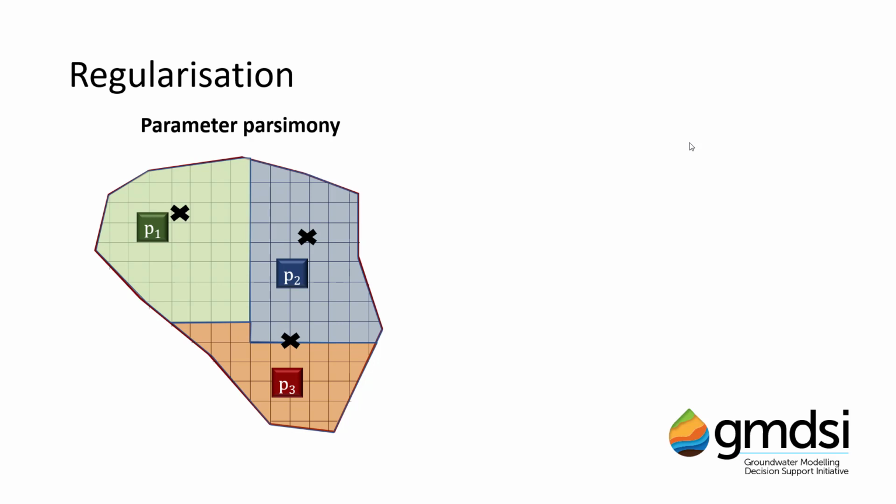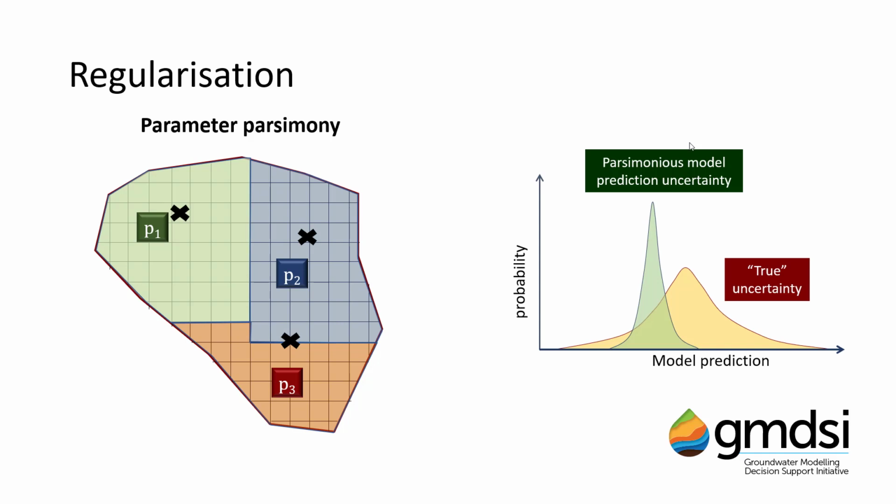These zones will have been delineated based on subjective choices by the modeler, and too few zones decrease the ability of observations to actually inform parameter estimation, which, as we've said, can result in model prediction bias. Such parameterization schemes may result in good fits with observed data. However, their parameter values are effectively very coarse surrogates for the complexity of the real world. Perhaps most importantly, by using few parameters, predictive uncertainty is often underrepresented.